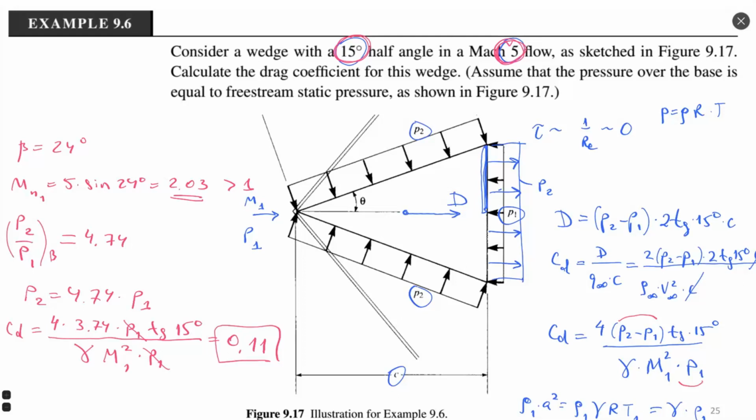You saw I made a transition from just the value of pressure. I made a transition from density and velocity to a dimensionless parameter such as the Mach number, and it worked quite well. We do not need any thermodynamic property to calculate the drag coefficient, just the geometry of our body and the dimensionless criterion of velocity, the Mach number.